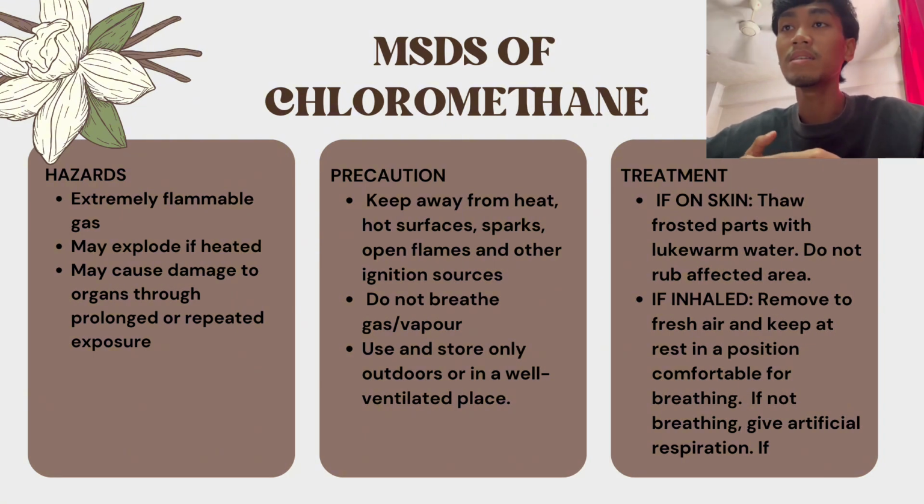First, MSDS of chloromethane. The hazard is extremely flammable gas, may explode if heated, may cause damage to organs through prolonged or repeated exposure. The precaution is keep away from heat, hot surfaces, sparks, open flames, and other ignition sources. Do not breathe the gas. Use and store only outdoors or in a well-ventilated place. The treatment is, if on skin, rinse frosted parts with lukewarm water. Do not rub the affected area. If inhaled, remove to fresh air and keep at rest in a position comfortable for breathing.